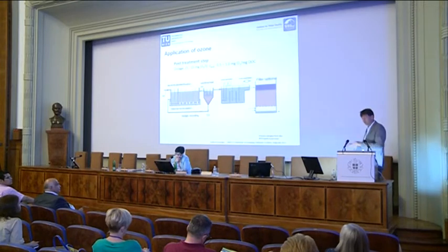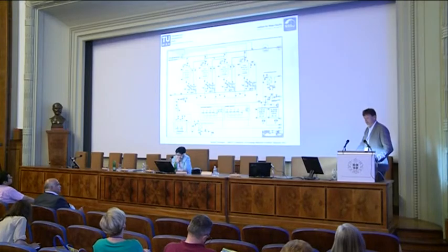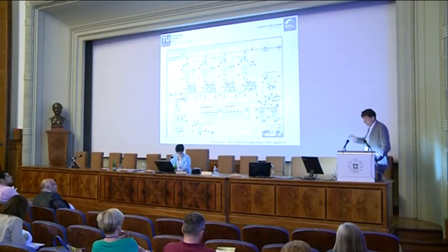So you want to reduce the DOC before you really implement it. That's what we are trying right now. So that's our plant that we are building at the moment. We have an ozonation tank, and afterwards, after the ozonation, we have 4 different options for the post-treatment step. Because it makes them different, we want to investigate post-granular activated carbon filtration, sand filtration,